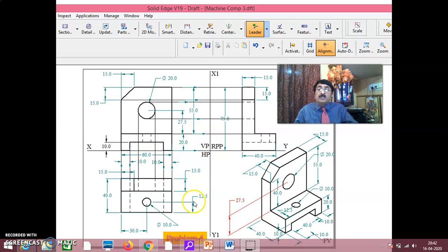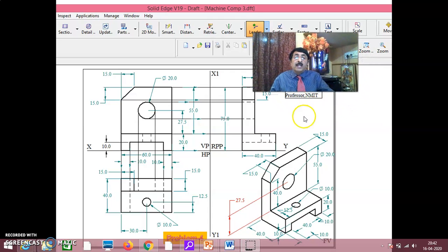Now once you do this, you see here, you are drawing the top view. You are looking from the top, and as you are aware, this edge which is going inside cannot be seen. That means 10 mm, 10 mm it is. When you are looking from the top, those two edges cannot be seen. That is, this edge going inside, this edge going inside cannot be seen. Now that 10 mm, see here, this is 10 mm, this is 10 mm. In that way, I have shown one dotted line here, I have shown one dotted line here also.